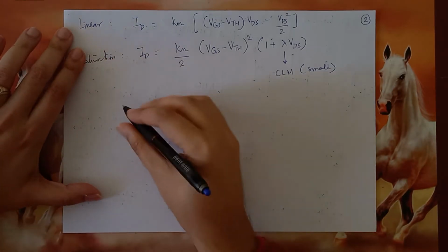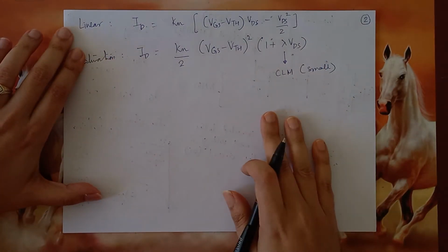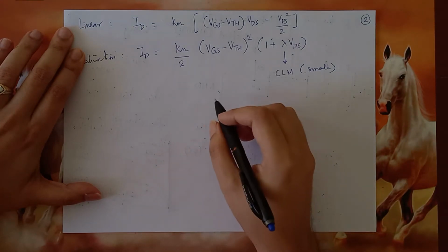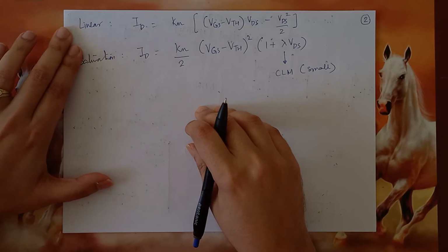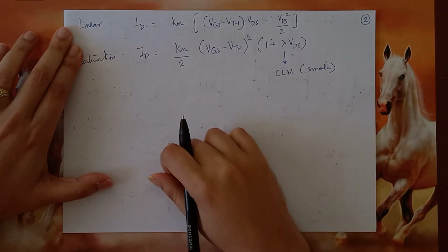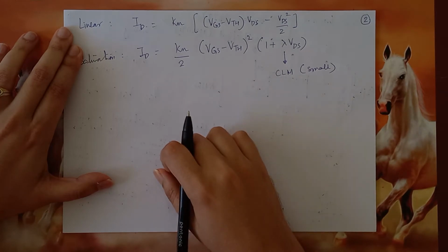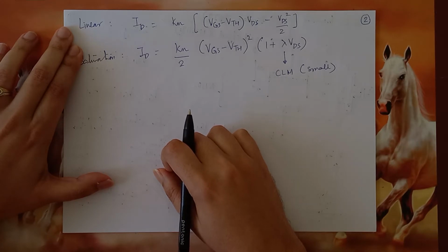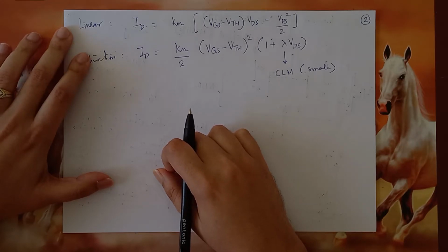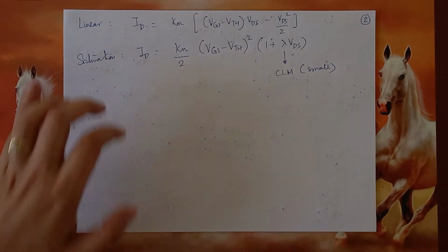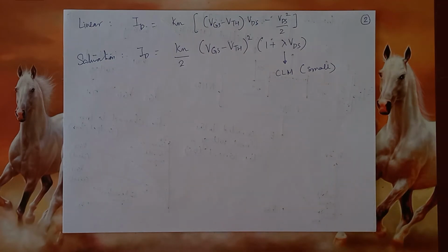As you know, if you neglect the body because it is connected to a fixed voltage, the small signal model essentially treats the MOSFET in such a way that it is DC biased in a proper way, and the AC voltage is so small in magnitude that it does not affect the bias conditions in any way.